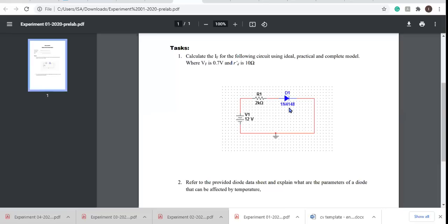If the resistance is so big, that means it is going to drop all the voltage across it. Yes, because my next question was the difference between RD and RR for its value. RD was 10 ohm and RR was 100 mega ohm. Yes, so okay, it's clear now. One is forward resistance, that is very small, and the other one is the reverse resistance, right?